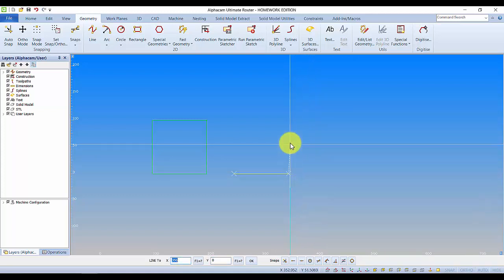I now want to move up, so I want to make some progress in the y direction, but not the x direction. So this point, you notice that the current reading down at the bottom is about 350, 100. So although it's not precise, it is close. So I can use that to approximate what the point is there. And it's going to be 350, tab 100, enter.